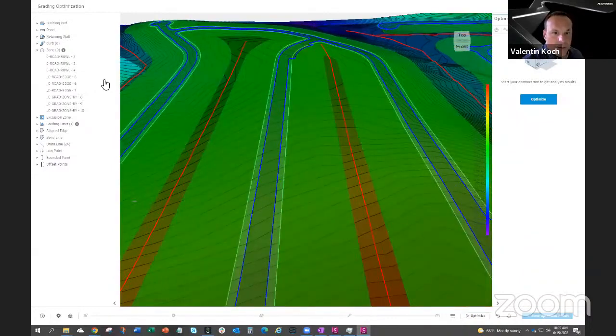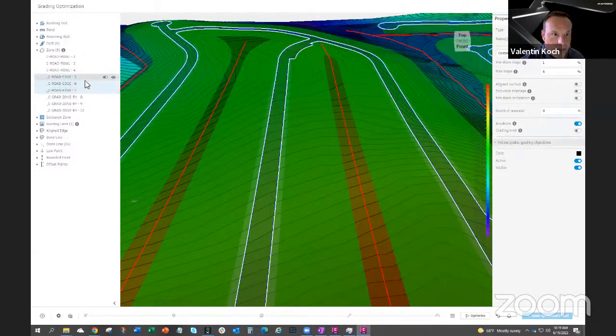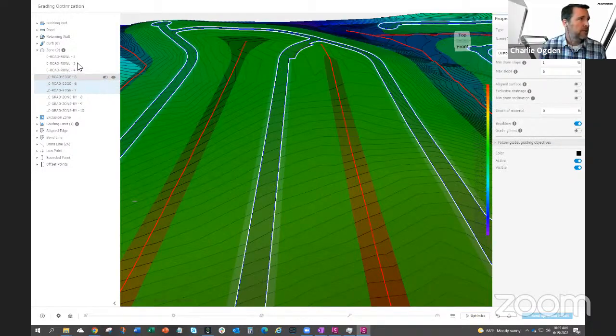So if one is, for example, the pavement, we don't want it to be overlapped by anything else, so we put it on top of the right of way, because the right of way is actually bigger than the pavement. So pavement on top, then right of way, and then the yard zones. Is that right there? Yeah. And these are, no, it's not right now. So these are my road pavement, the road edge, so my pavement.